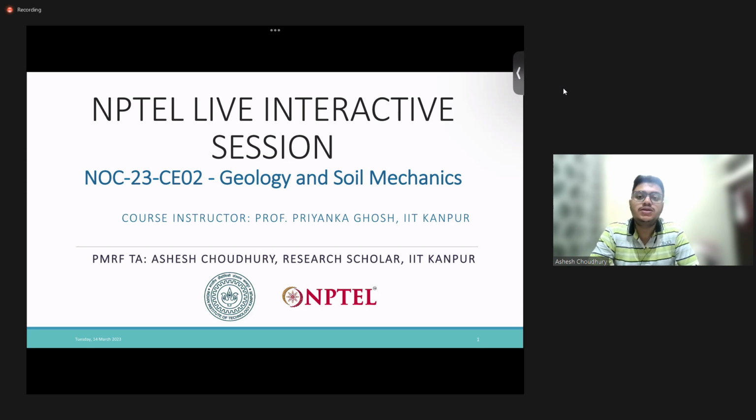Consolidation is a very time-taking phenomenon. It takes many years for the soil to obtain 90% plus consolidation. There are many ways in which we can accelerate the process of consolidation, and we will study those towards the end of this chapter. To name a few, some techniques are preloading and the use of vertical drains, which are used extensively nowadays in practical scenarios. So now let us start.